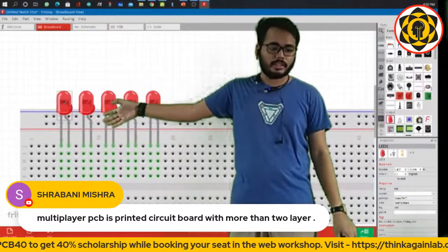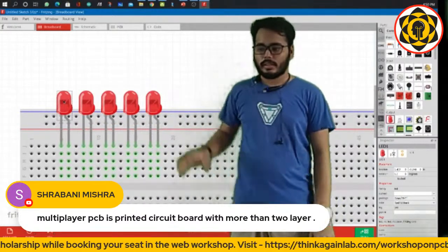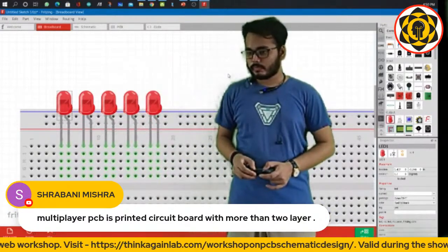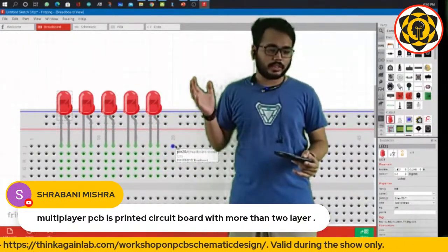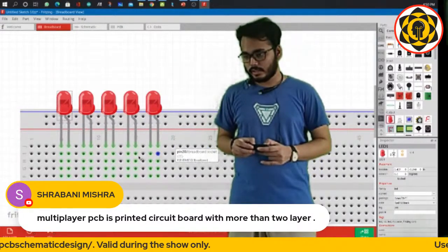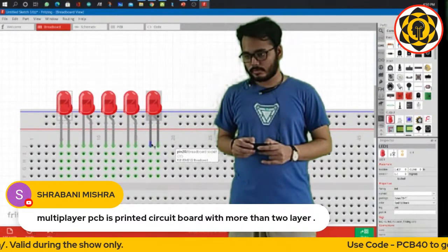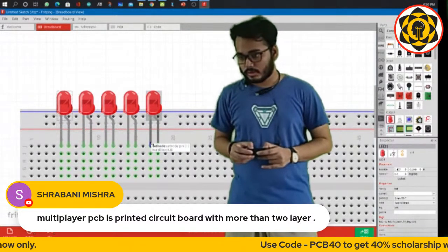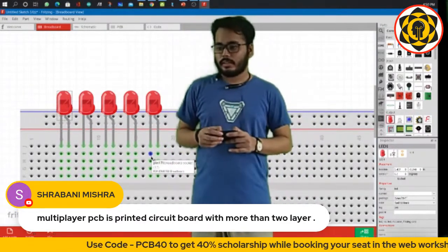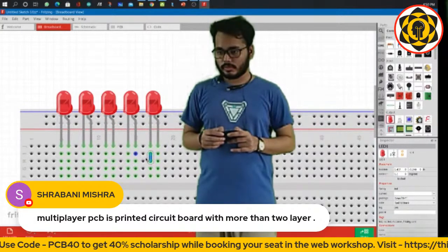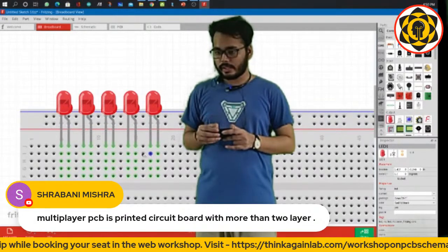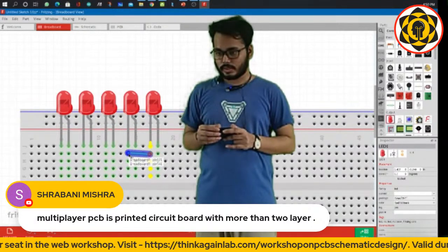I have 5 LEDs here, and now we can connect them to the Arduino, and then we can start developing the other stuff. First, we all know that the ground connection of the LEDs is a common one. So let's first do that. This is the ground, if I'm not wrong. If you just point on the limb, it will show you. Yeah, it's a cathode pin. Now I will connect this ground. You have to hold it and drag it to connect. Like so.